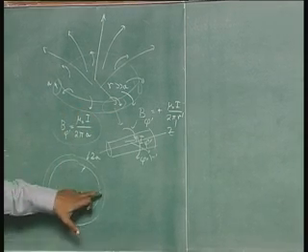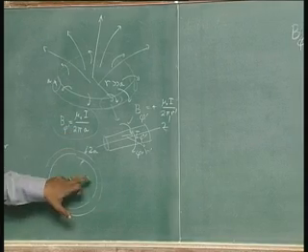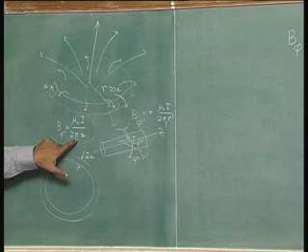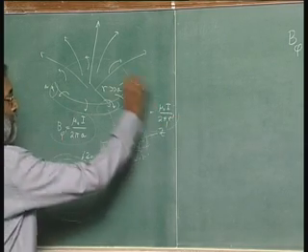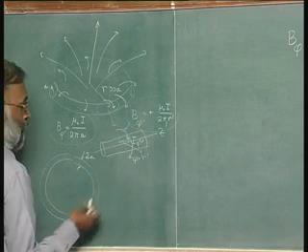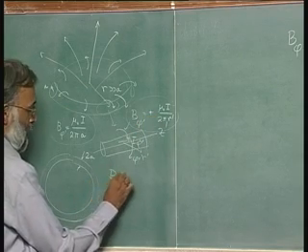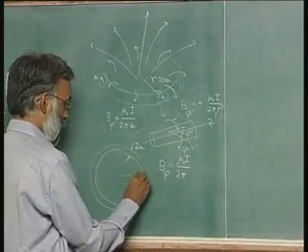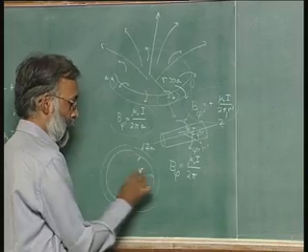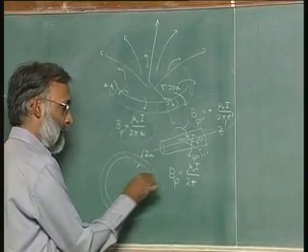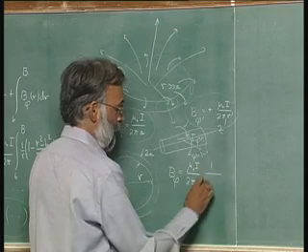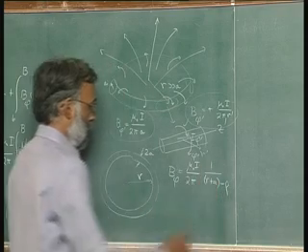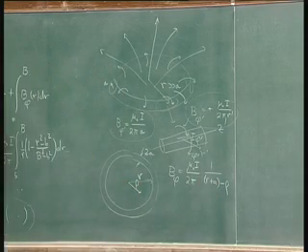It is not really valid except very close to the wire, but away from the wire this is actually an underestimate, because of the bending of the wires, this field will be higher than what I would get by using this formula. So, using this formula, I get that B phi is equal to mu naught I over 2 pi, this radius is r, and the magnetic field is in the reverse direction, so 1 over r plus a minus rho, where rho is my general coordinate.